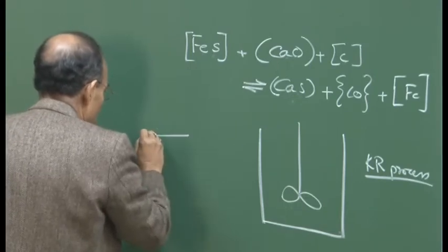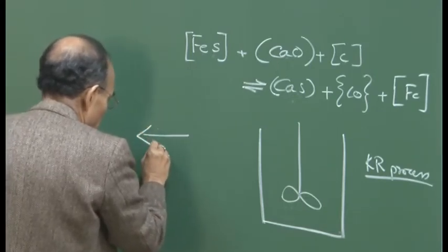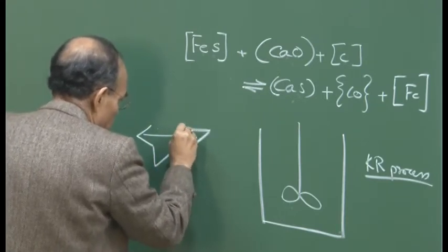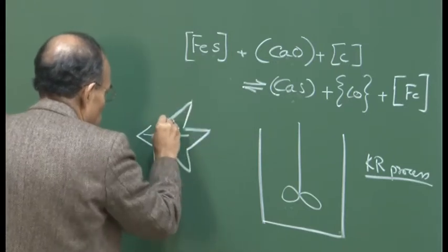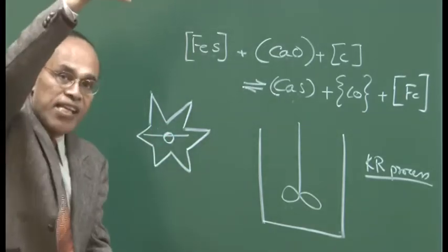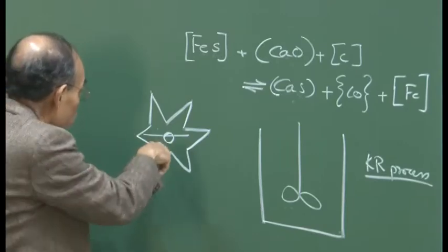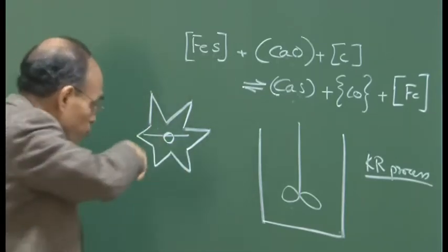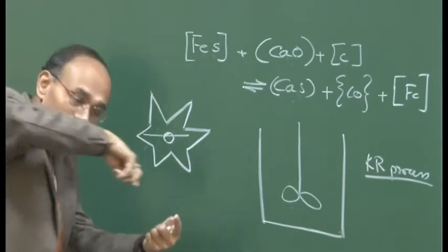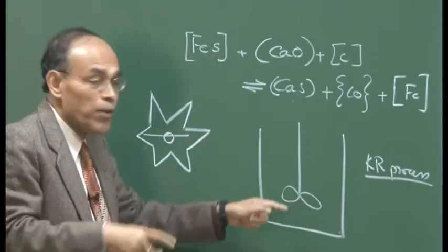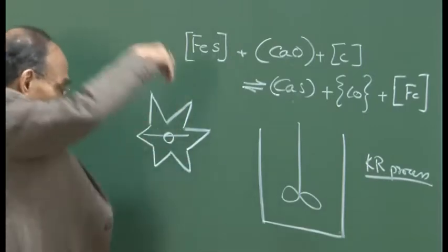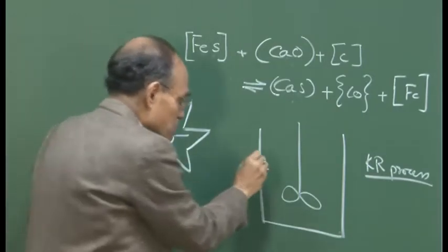So, that is the design; my drawing is not that good. This is the way the propeller looks, okay, and it is a refractory propeller with this kind of shape, because when the propeller rotates, the fluid wants to be rotated, so you have to create the maximum surface area, and this provides a very large surface area. Then the kinetic energy of the propeller can be very easily transported to the melt phase, and it can impart a good amount of motion. So, this is the top view of the propeller. So, we stir this vigorously.